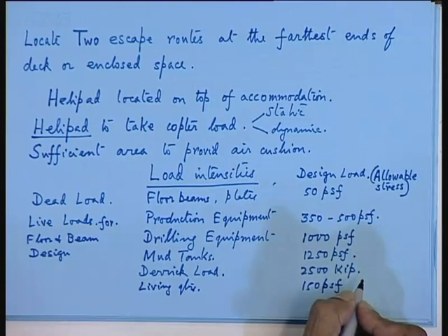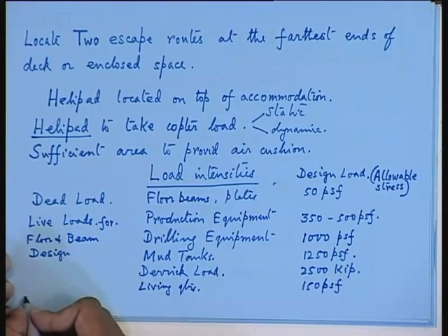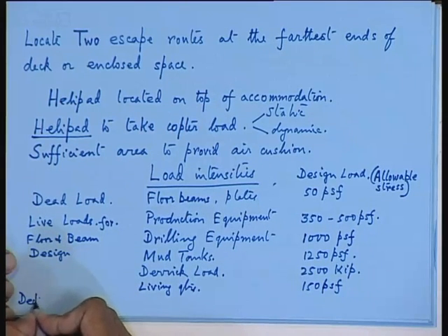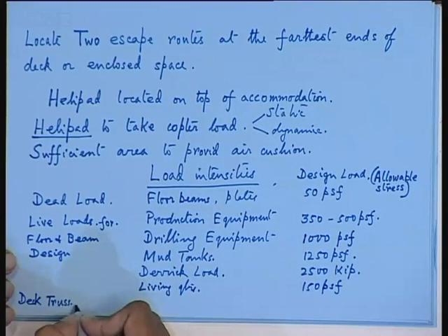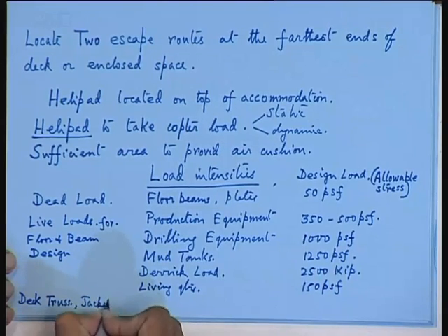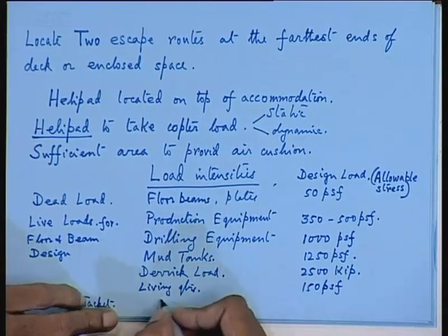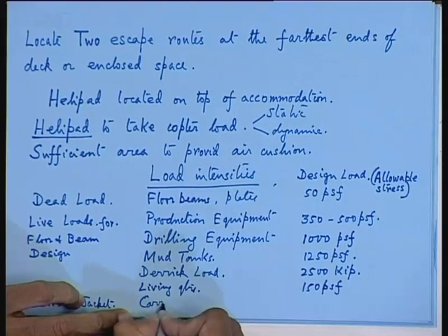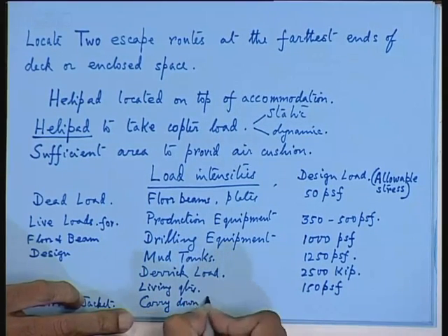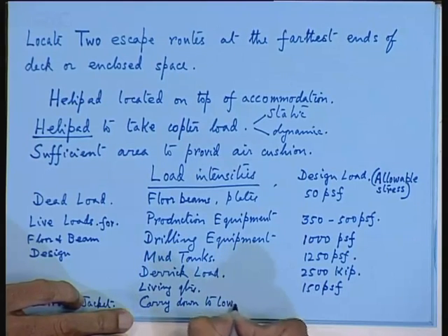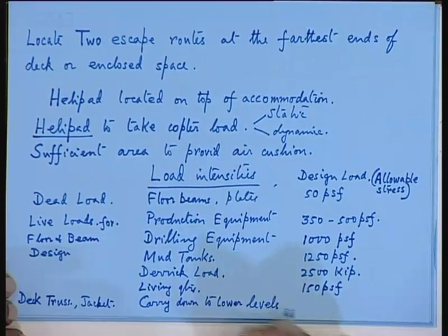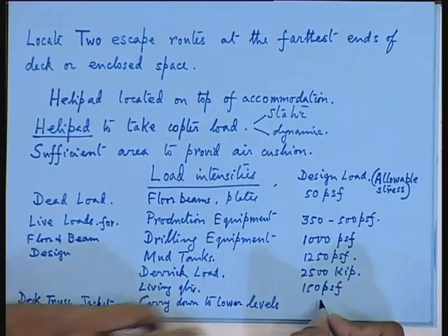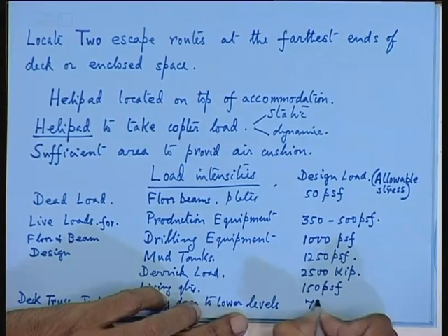Now, after you have designed this, now the deck truss, the supporting truss for the deck, jacket. So, these are carried down to lower levels. Carried down to lower level means your deck load is ultimately coming to where? I think you are not able to see this, no? So, this is 70%, you take 70% of live load.